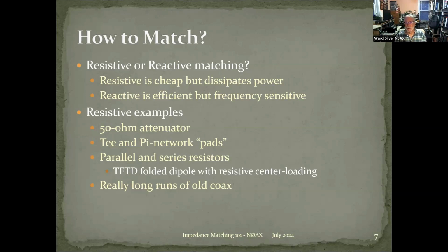That's why you use these attenuator pads in audio systems. And if you look at a lot of radios, you'll see a 3 dB pad or a 6 dB pad or something like that. They present the same impedance on each end, but they soak up some of the signal. That's what's in your receiver as an attenuator. But typically, we don't want to burn up RF power. RF power is expensive, whether you're trying to receive a really low signal or whether you're trying to put out a really big signal. You don't want to throw away your RF.